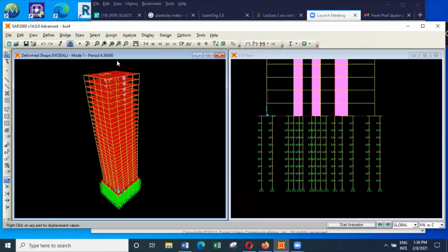And sometimes when you want the natural period of vibration of the structure, you might actually apply a set of supports at the ground level and determine that. The reason is, in the actual structure, we have soil here that we have not modeled fully.